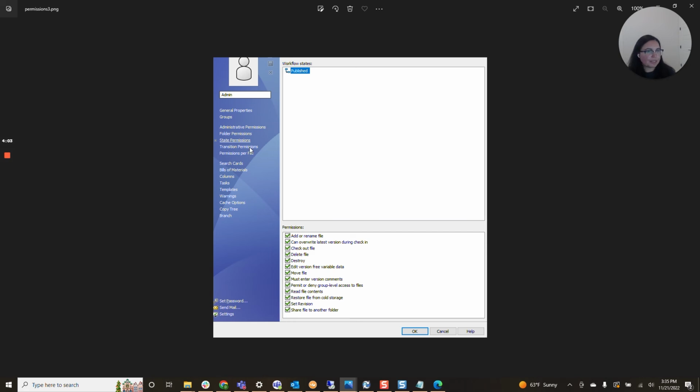This one's a little less cumbersome, and it very much depends on your workflow and how you want to structure those permissions. But definitely recommend making everybody adhere to a group structure so that if you're granting document services users the ability to release files, it goes for all of your doc services users uniformly.